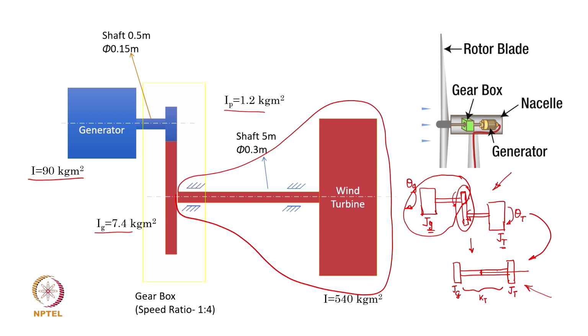So, this turbine rotational speed and the degree of freedom corresponding to it is now fixed to theta t, and now look at how this particular shaft which is connecting the generator to the pinion, which is basically this particular part of the shaft, when you align or connect it directly to the turbine, obviously the corresponding twist is going to remain the same, and basically the strain energy associated with the twisting of the generator shaft here should be scaled, so that